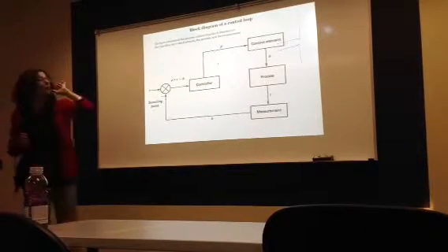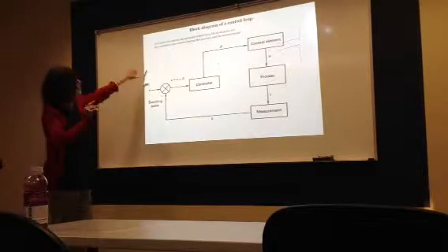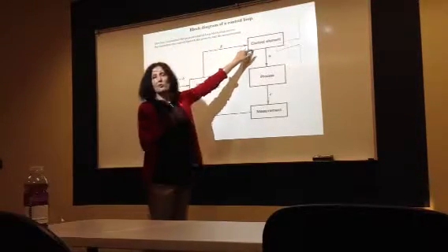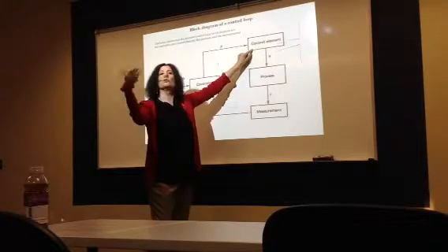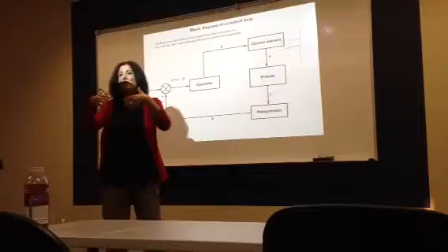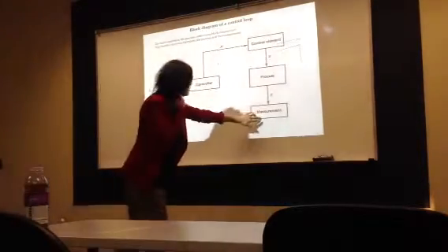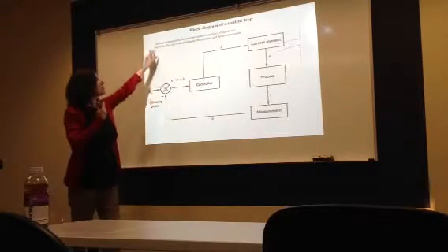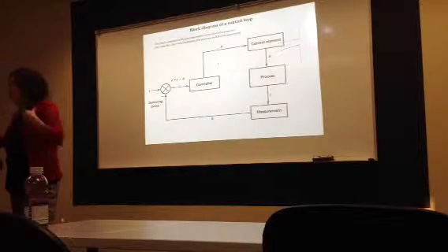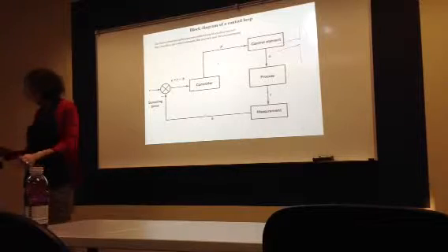Now, block diagram of control loop. We talked about it many times. What does it have? Controller, control element, final control element, which could include the actuator to act on the final control element, the process itself like heating, temperature, tank level, and then we have the measurement, and then we get there. So the basic elements in the process are whatever you see here: the controller, the control element, the process, the measurement. Okay?